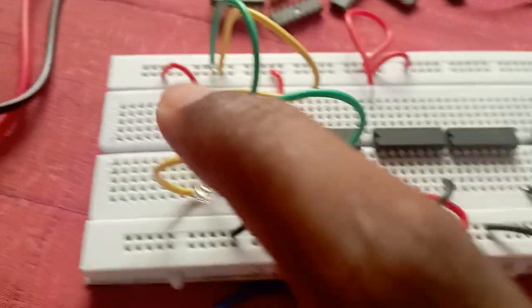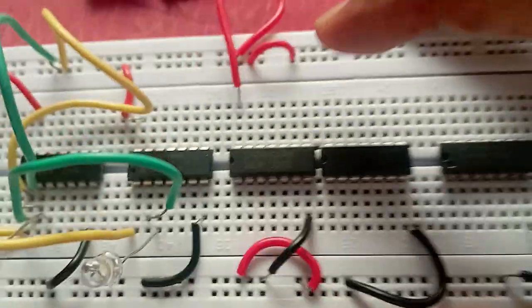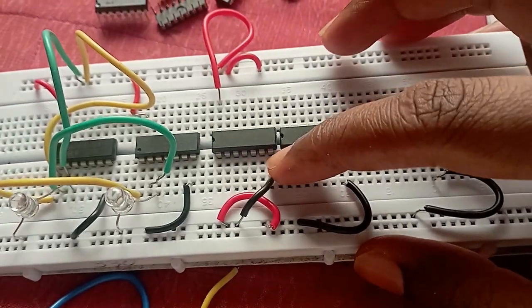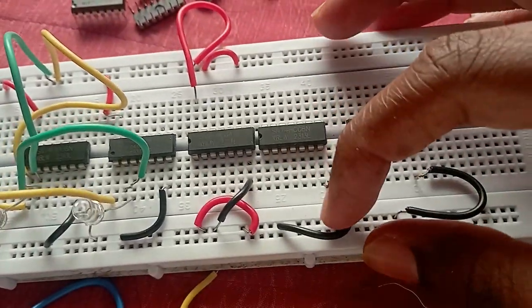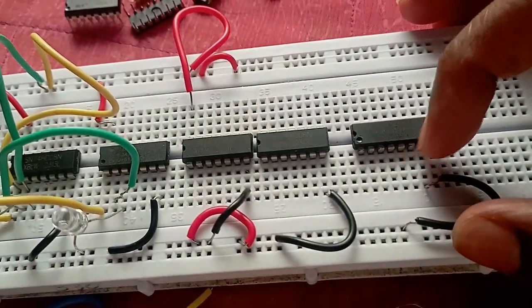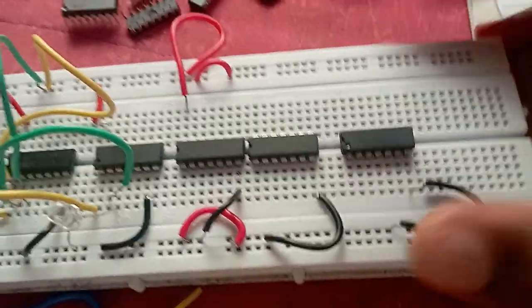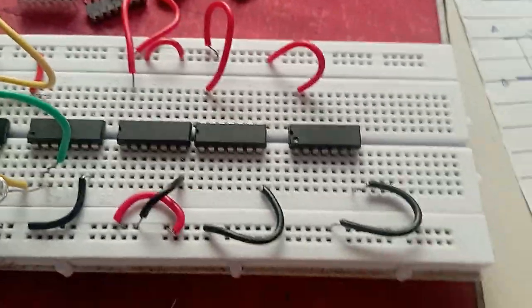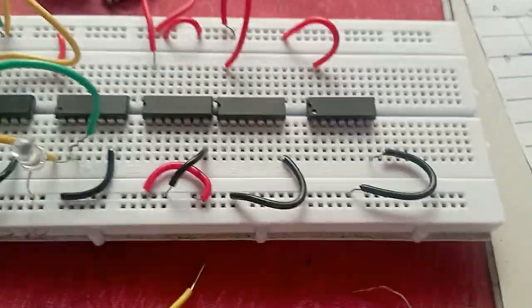As we connected in this, first we will connect the 14th pin as VCC, which I have connected, and the 7th pin as ground. And again here the 7th pin is on ground and the 14th pin is VCC, 7th pin on ground, 14th pin is VCC. Always the first connection is of the 14th pin and 7th pin of every IC.